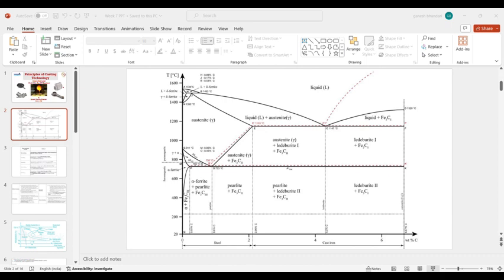No, it is not for that, because we are talking about quenching. So this salt solution, in industry the term used is brine solution. So what will brine solution provide? Brine solution will provide high conductivity during your quenching process, and it will not create much thermal stress in your system. That will help to some extent if you are going to quench it in your salt solution.